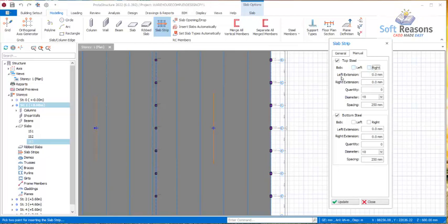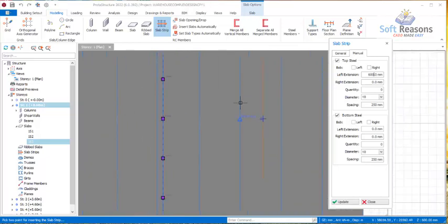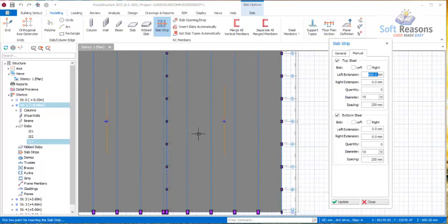Okay, so for the extension, like the first left extension, you have to give an extension to the left, like the lap length. The lap length could be 600. So if you are to have a kind of continuity, just like in this provision where you have an expansion joint, there must be continuity. So there's supposed to be a lap length that you give to the reinforcement successfully. The program is going to automatically incorporate this into the full length of bar, which is 12 meters, to ensure that there is proper continuity as you carry out your design.